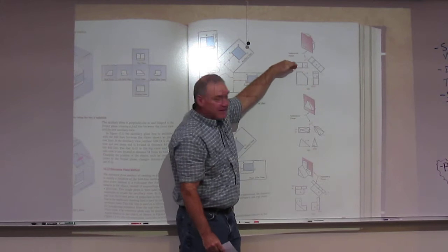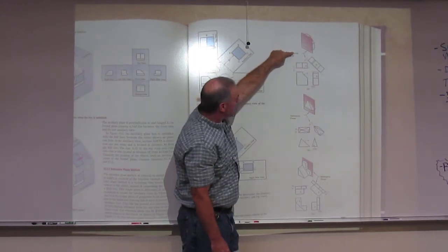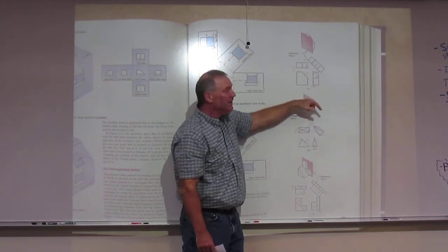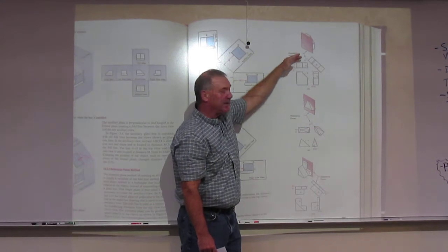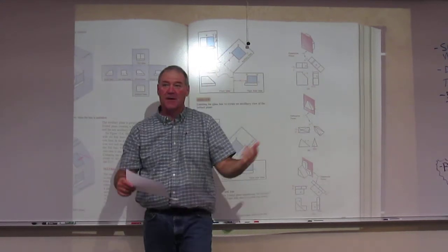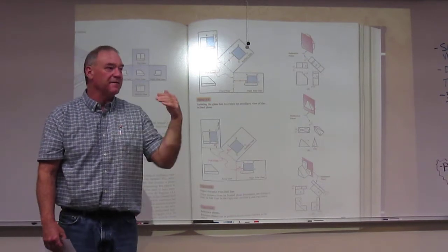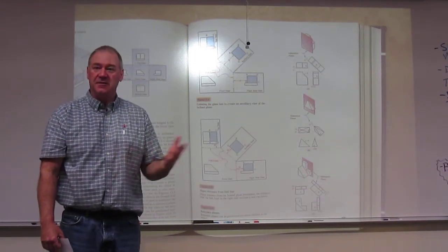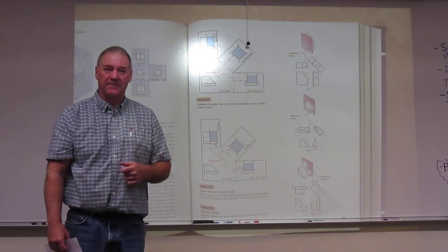Now, I picked it here so that I can say, well, I know it's here, but depth goes this way, depth goes this way. Can't I just measure from that plane to there, and then it will have to be the same in all views? And then, yeah. That's in essence what we're doing. We just picked an existing plane on an object and use it like a fold line, because it's still giving us a depth reference.